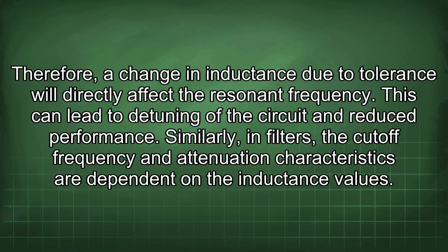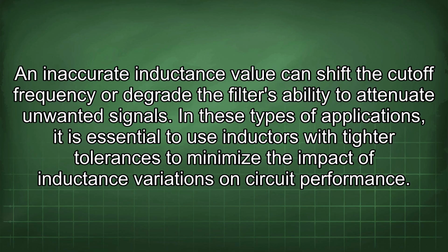Similarly, in filters, the cutoff frequency and attenuation characteristics are dependent on the inductance values. An inaccurate inductance value can shift the cutoff frequency or degrade the filter's ability to attenuate unwanted signals. In these types of applications, it is essential to use inductors with tighter tolerances to minimize the impact of inductance